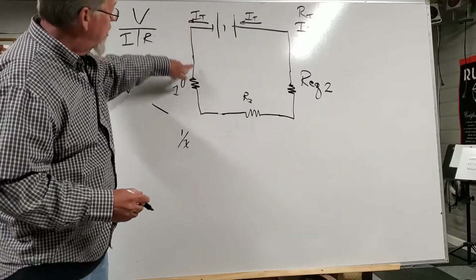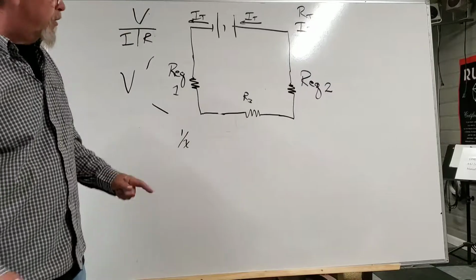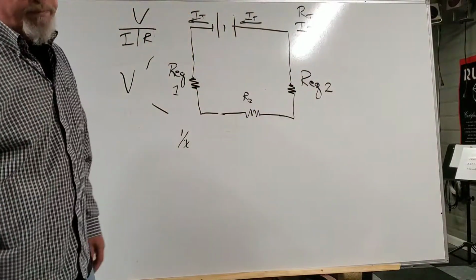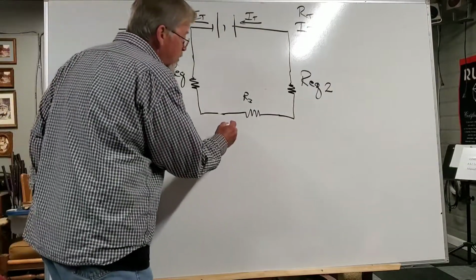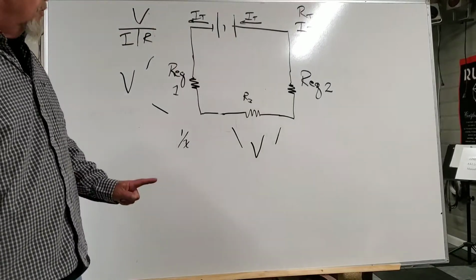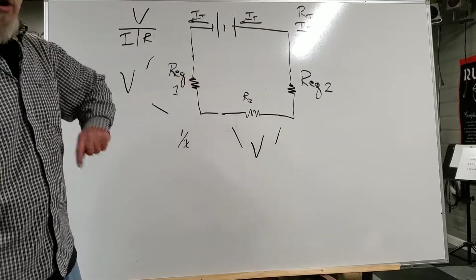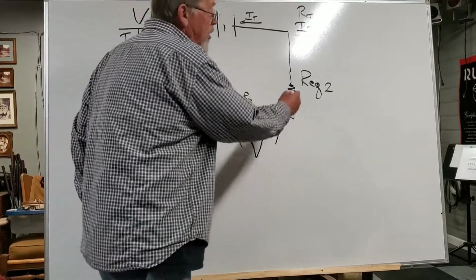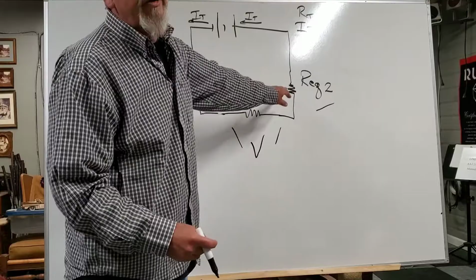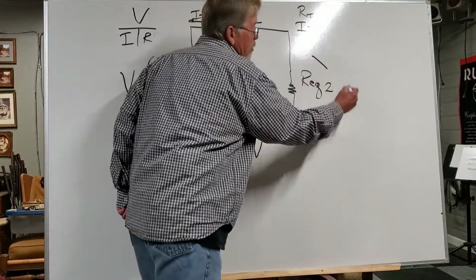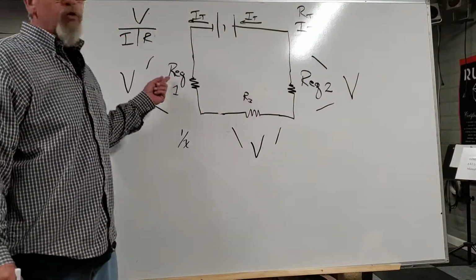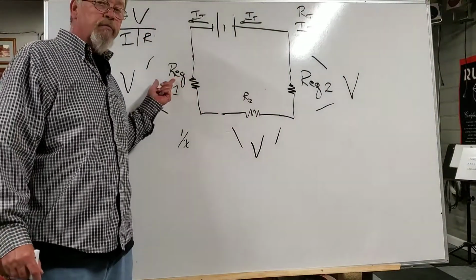And then that same total current is flowing through R3. So you know what? I can write that the current for R3 is the total current, the same. And then I can find the voltage across R3. And you know what else? I have current flowing through R2, the equivalent resistance of R2, and I can turn around and find the voltage across it. And look, if I know the voltage across REQ1, you know what I know?